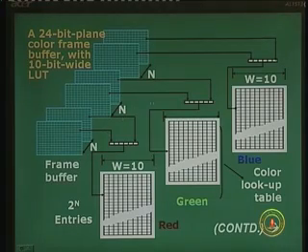1024 or 1k, I am sorry, I talked about 1 meg, it is 1k values. Out of those 1k possible values, which you can assign onto the lookup table, the programmer a priori chooses 256, or 2 to the power 8, possible values and loads the lookup table. Why 256? Again 2 to the power n. As we look into the figure, there are 256 possible entries, but each entry is 10 bit wide.